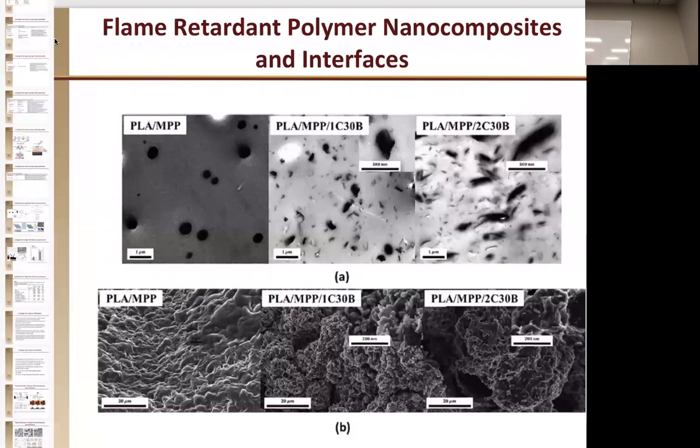See how it's really carbonized down here. But notice the microstructure here. This is where the clay platelets that were burned out around are starting to form that char layer. So we have a structured foamy char layer created by the montmorillonite plates at two different loadings. This is going to be heat resistant and have less heat flux because of the high layer. Here, this is bare polymer.